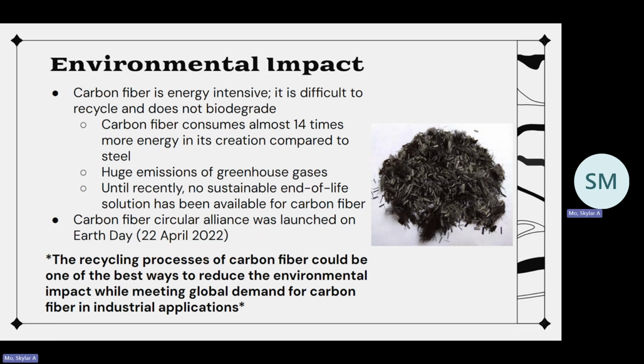So another consideration is the environmental impact. Carbon fiber has the potential to have a heavy effect on the environment because it requires a long and complex manufacturing process. Carbon fiber is also very energy intensive, and it is difficult to recycle and it does not biodegrade. Carbon fiber consumes almost 14 times more energy in its creation compared to steel, and carbon fibers exhibit huge emissions of greenhouse gases. Also, there are no sustainable end-of-life solutions that have been available for carbon fiber.